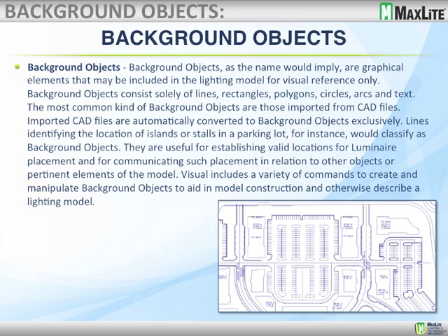We cannot give you that much of a detail. Well, if they want this type of detail, they'll have to supply a CAD file. Is that correct? Correct. AutoCAD or even a PDF, a very clean PDF file. The PDF can be converted with the software that we have into a DXF and then brought into our lighting software. A lot of times if the PDF is not clean, there's a lot of pixelation or a lot of white noise, as I call it, and this takes a lot of time for us to clean up the drawing itself.